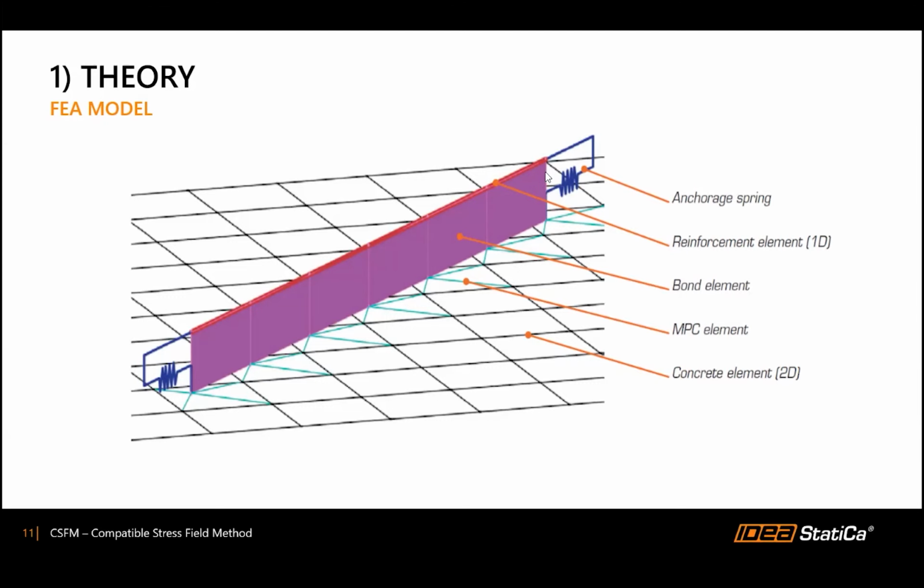At the end of every rebar, the rebars can have different anchorage shapes. There can be a hook or a loop, and it's mirrored by the spring at the end of every rebar, and it changes the anchorage length. If you have a straight bar, there is a different coefficient than for perfect bond, or for a hook or loop at the end of the rebars.